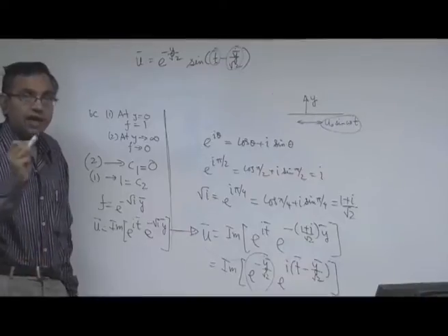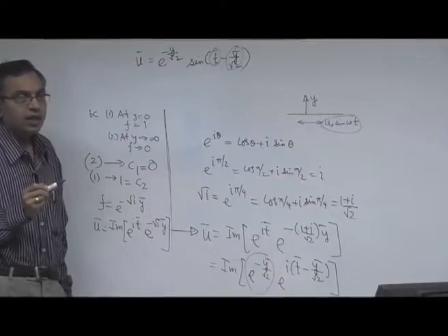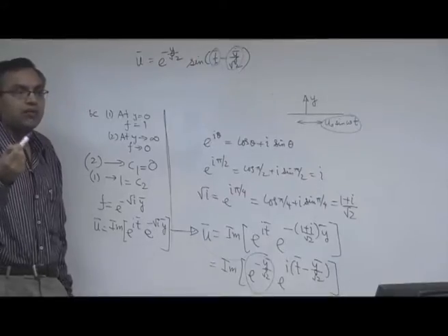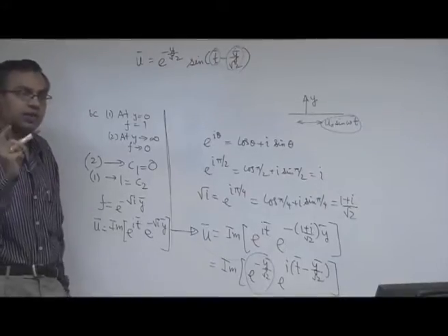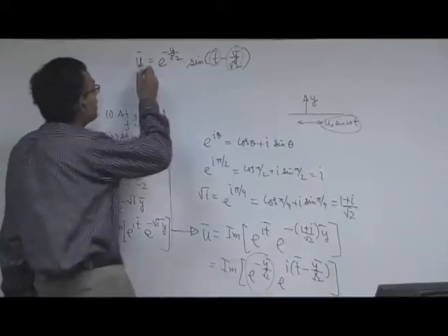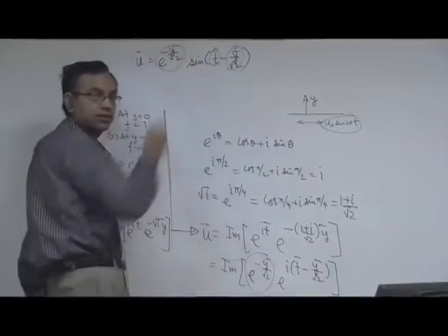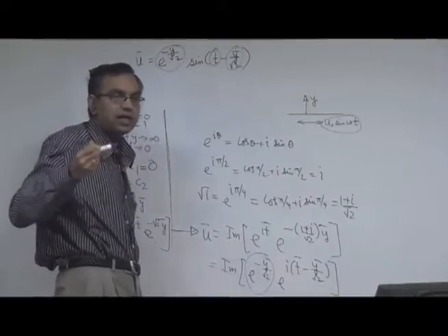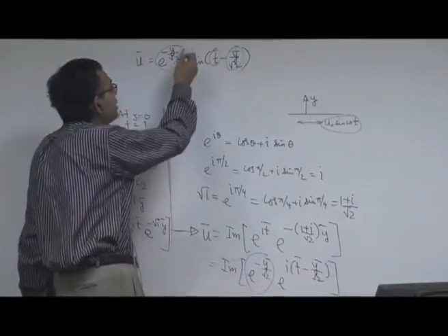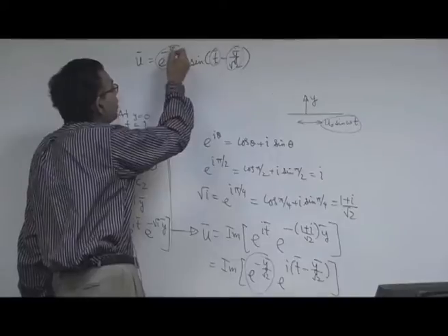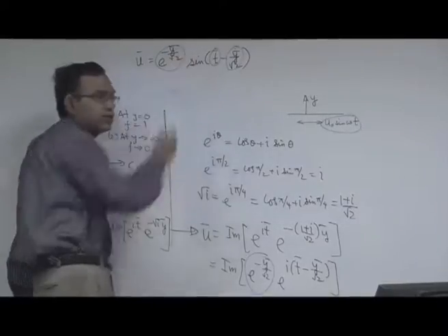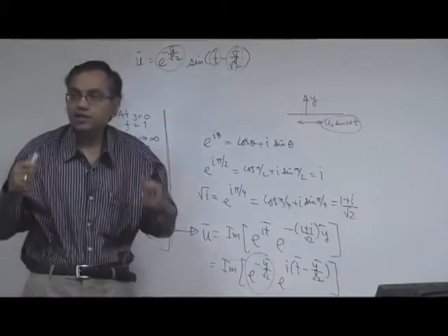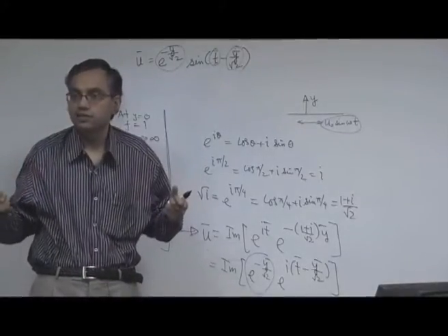And what is the amplitude of oscillation? If there was no damping effect, then the amplitude of oscillation would have been the same, that is u0. So, in that case this would have been 1, but because of the damping effect which varies exponentially with y, you can see that the amplitude now becomes, this is y bar basically, e to the power minus y bar by root 2. So, it is a situation like a damped oscillation.